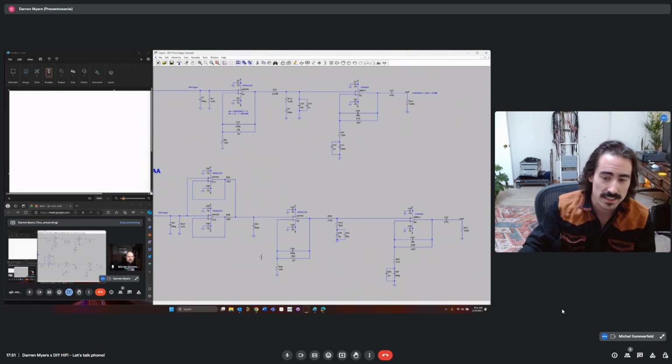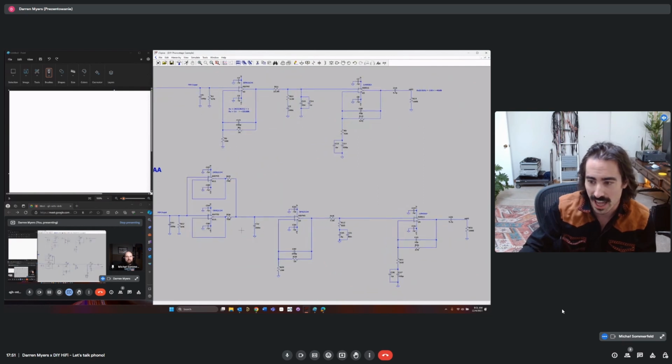Sometimes adding another parallel amplifier discretely is not the most advantageous, depending on the type of amplifier. But with your ICs, you can just use the other channel of the 2134 and have one 2134 per channel.